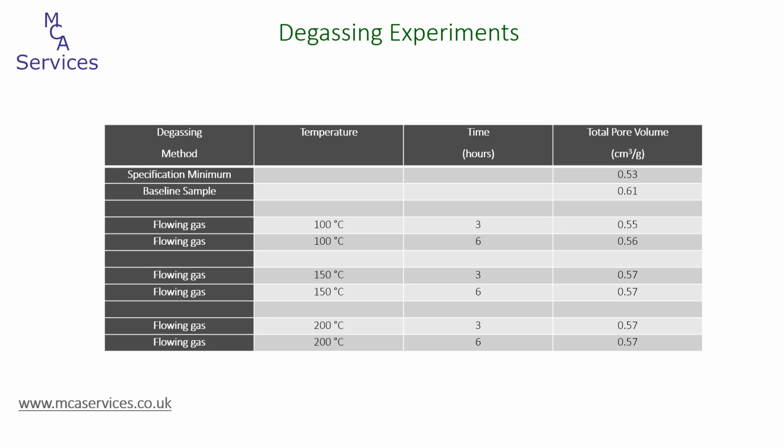Now, as pores become larger, the increase in surface area, that is to say the surface area of the walls of the pores, actually decreases relative to the increase in volume. It is therefore reasonable to observe some disparity in the relationship between surface area and pore volume when comparing results. And it shows the necessity of considering the effects on both pore area and pore volume of extraneous volatile substances.